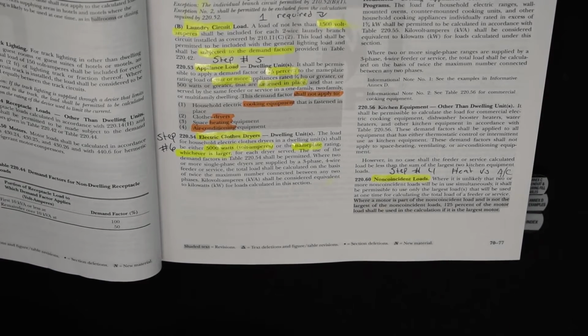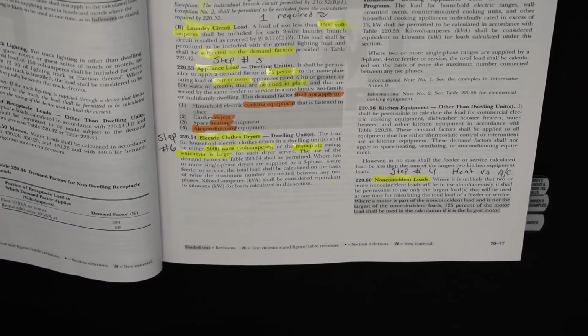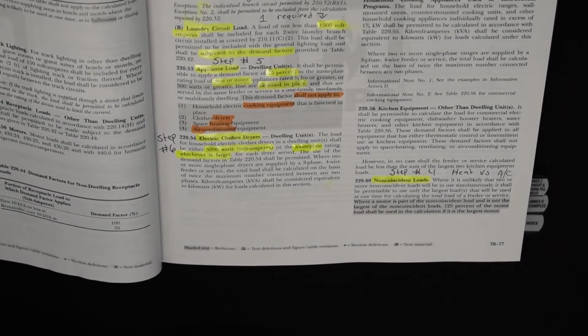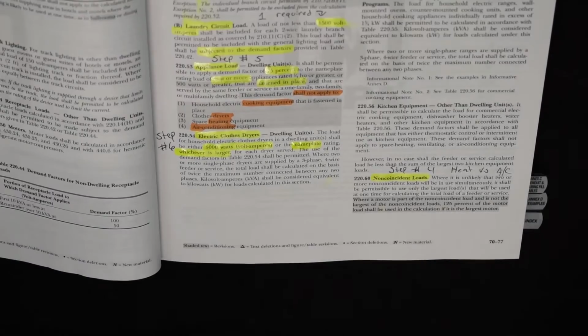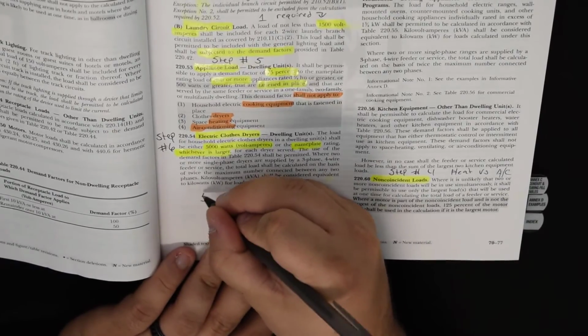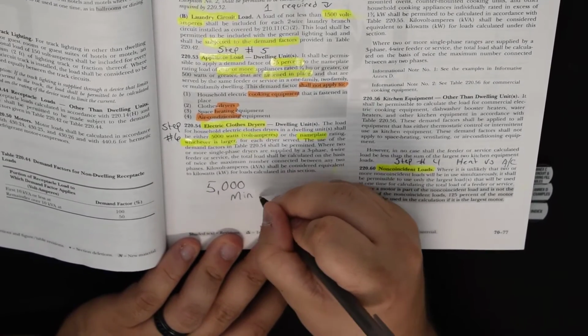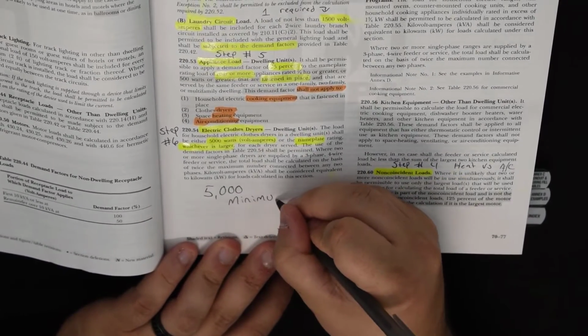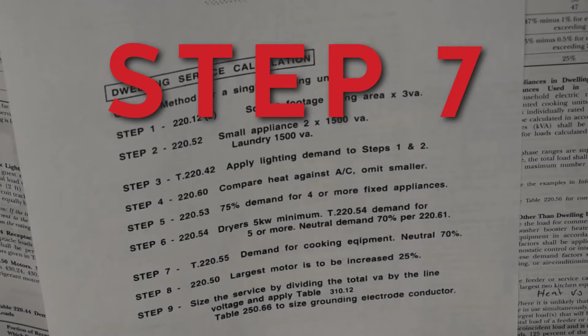The important part here is no matter what the nameplate says, we're going to account 5,000 unless the nameplate says more than 5,000. If we have a 3,000 watt nameplate, we're still going to put it into our calculation as 5,000. Doesn't matter. So to help that understanding for your knowledge to use this code book, down at the bottom we've got a little blank area, write 5,000 minimum. Then we're going to go to step number 7.